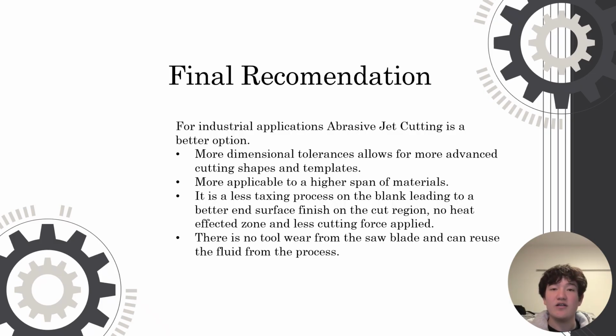It also is less taxing on the actual blank or material you're cutting, which can end with a better surface finish, cut region, and no heat affected zone at all. Finally, the biggest application I would say is that there's no tool wear. You can reuse the products over and over, allowing for it to be basically no cost other than just running the product.